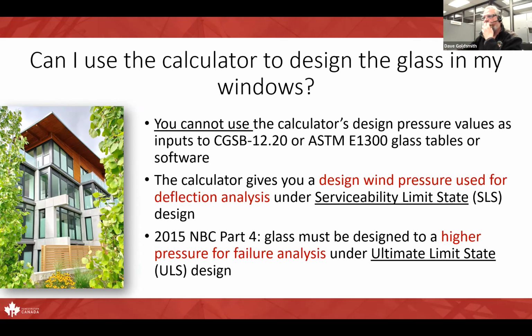Based on an input from the output of the software, it will give you the strength of the glass, what its capacity is, and it'll also give you the deflection of the glass. And it warns that deflections greater than 18 millimeters may be of a concern. So as you know, Al, tempered glass is very, very strong, but is not any more rigid than annealed glass.